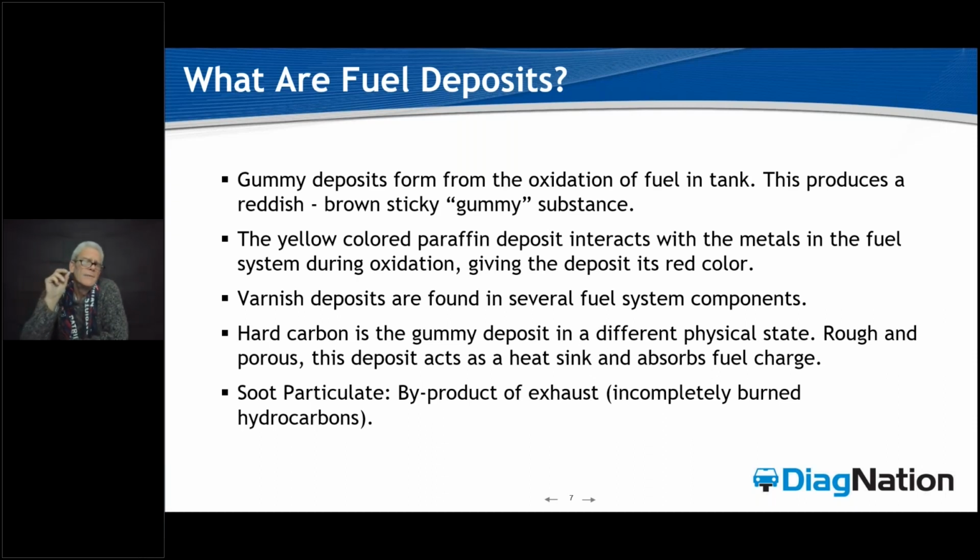Now, considering that, we've got some issues post-combustion that can creep into these vehicles, such as switch time codes, slow O2 and air fuel ratio sensors, and then of course, depositing on the catalytic converter itself, eventually leading to a clog, right? So if you think about these deposits in terms of gummy deposit, varnish deposit, hard carbon deposit, and soot, now we've got a picture of what is cycling its way through the engine right now.